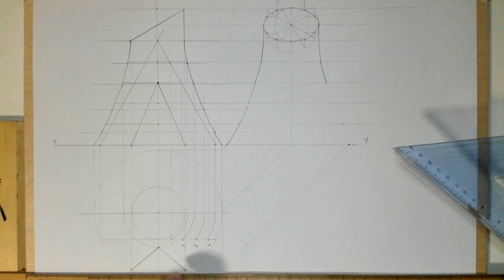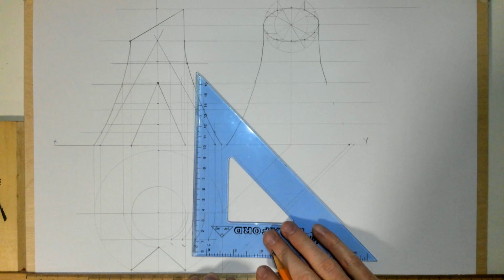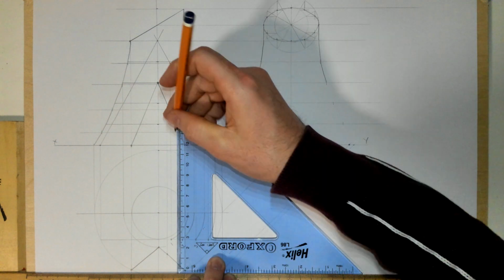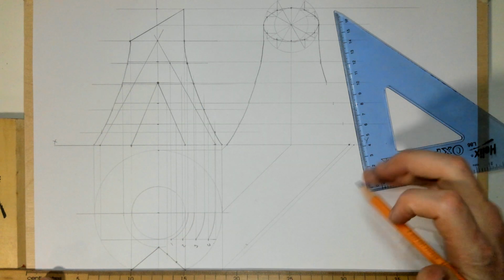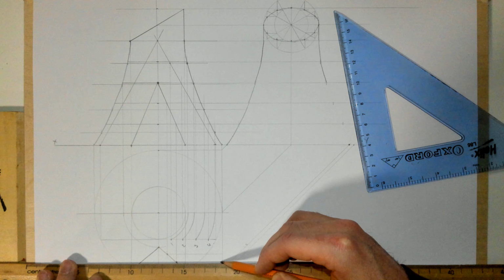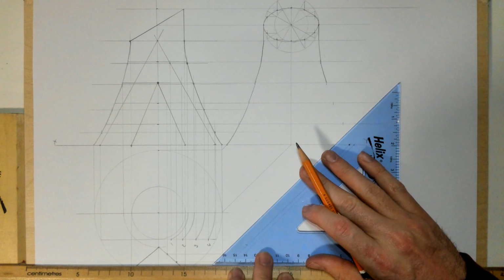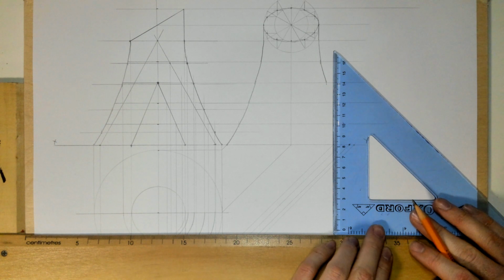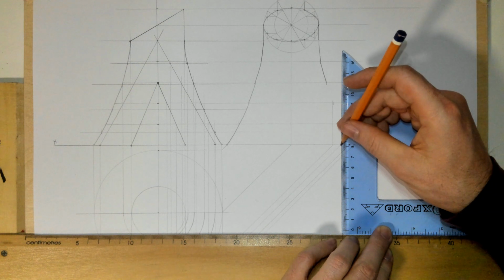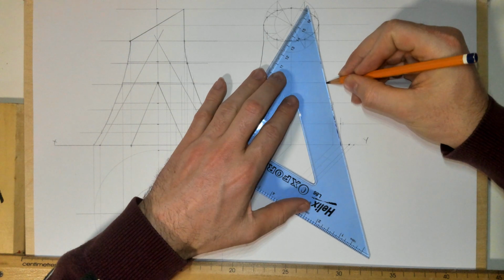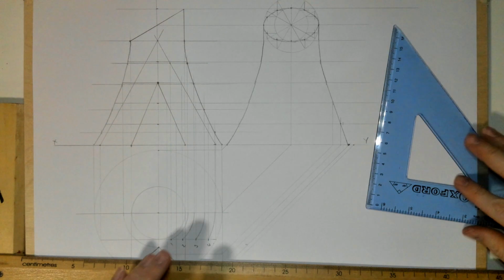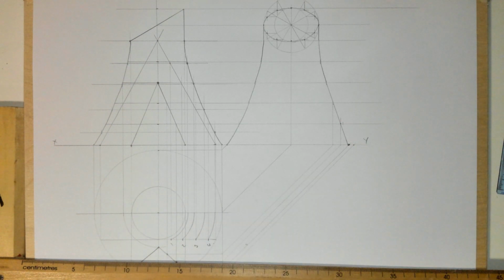And to get where it goes out for each one, we need to bring them across. So that point there in that view gives me that point in plan, and same with that one. So there are the outer edges. If we bring those across now and up to the end elevation, that will get the proper or true side profile or end view of the object, because of that cut section there at the front. So it should be in a little bit further. It's almost in the same line there for that one, and that one there cuts in a little bit further. Now, I'm not sure, it should be a straight line going between them, or close to straight down to that point there at the bottom. So the right hand side is a little bit different because of that cut section there that we were given. Okay, that's part B of the question finished.